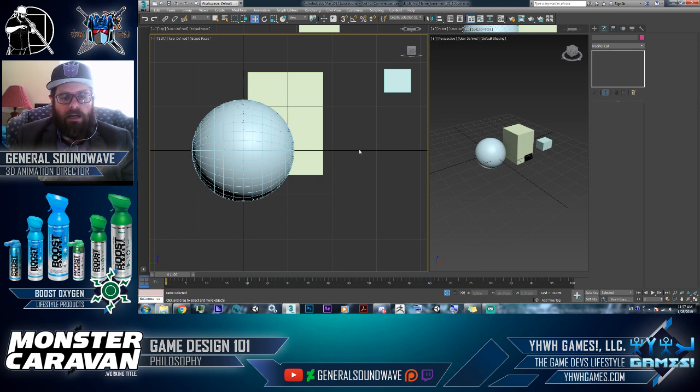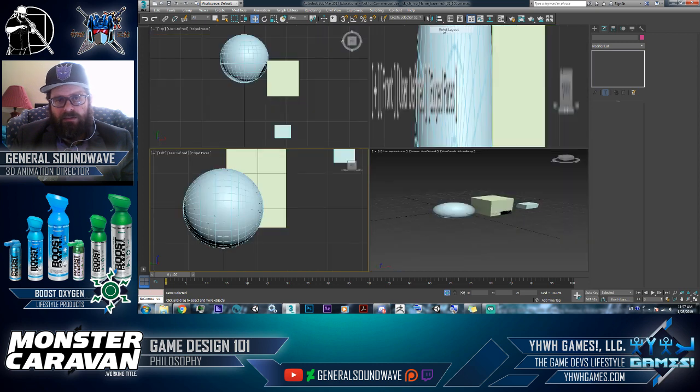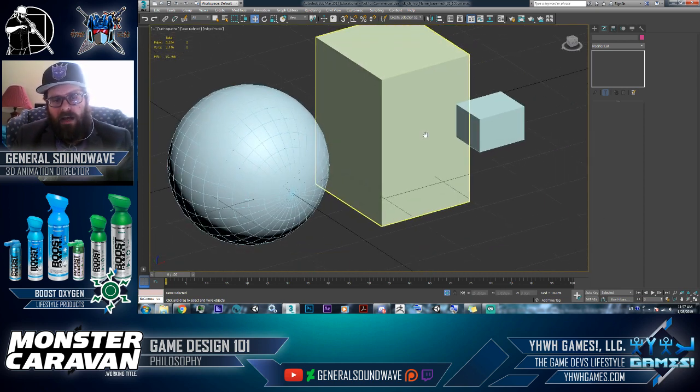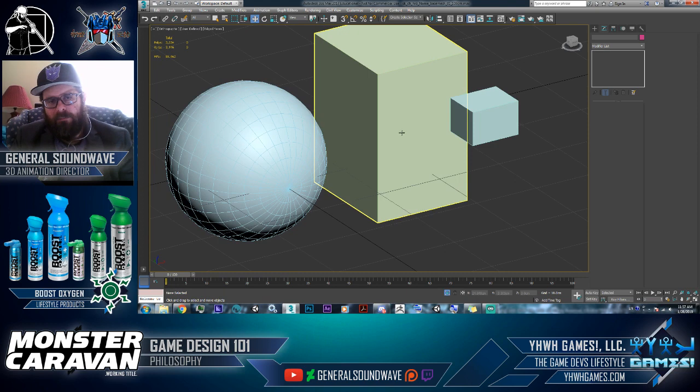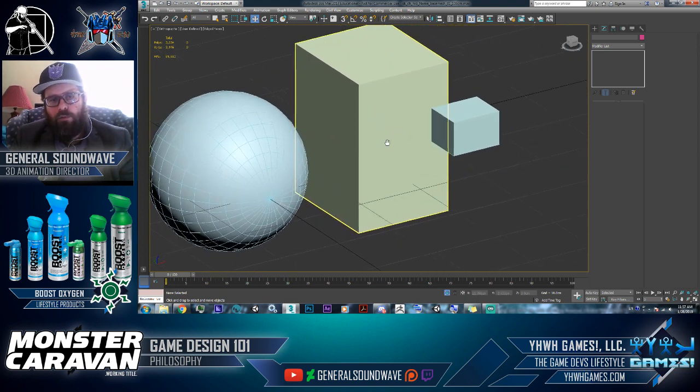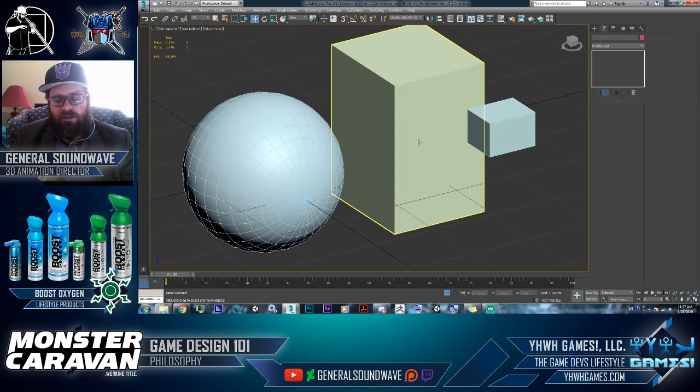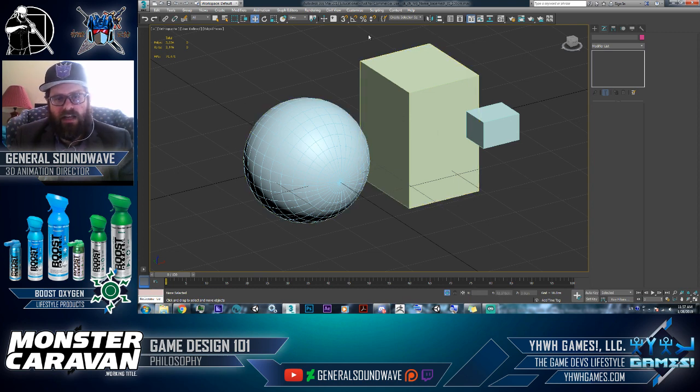Okay. So what we can do is right click on the reset layout for later, go to the front viewport, maximize view, and now all of a sudden I'm in three axes by holding the Alt button, pressing the middle mouse button, and I can do like this. I can click and move my mouse, or middle click and move my mouse, and I can get panning. I can also zoom in and out. I can also hit Z on the keyboard, and it tries to center everything up to the best of its ability.